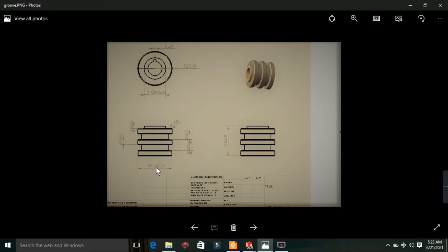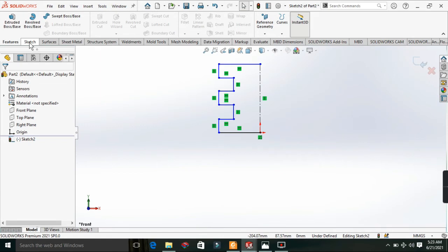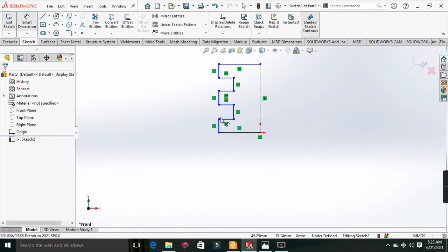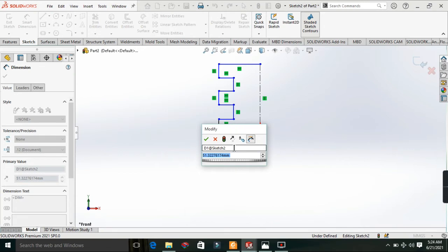So we said from this place that you divide it into two. So 143.01 divided by 2, you said 71.51. So go back to your sketch and dimension it, because half of that 104 is what you want to get here. I explained to you that we assume we draw a center line from the middle. So you write your 71.51, then you click on OK.